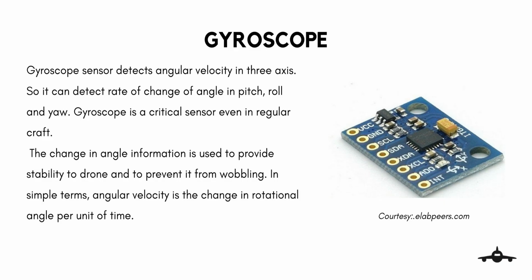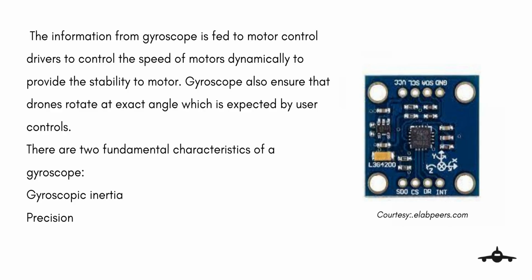Gyroscope determines the rate of rotation, or you can say angular velocity and tilt. It measures angular rate in all the three axes. It is called a vibrating structure because when rotating the gyroscope on an axis, by the Coriolis effect, a vibration is produced that is measured by capacitive plates. The signal generated by the plates is treated to be proportional to the angular velocity.